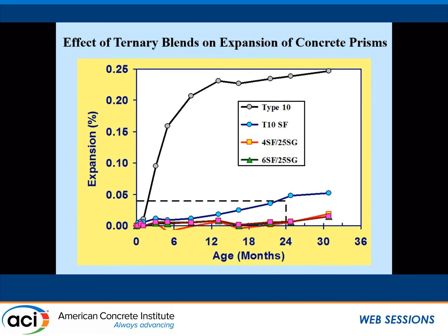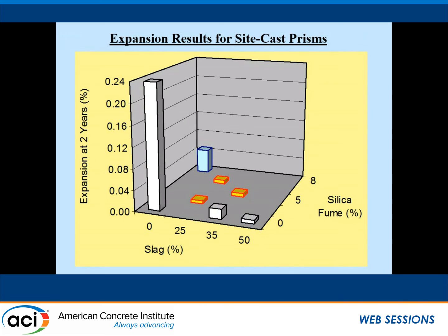The last time I looked, only the control mix was showing any kind of surface cracking or deterioration. So all of the blended cements have worked up to about 15 years. Obviously, time will tell if they'll be effective very long term. And that just shows the expansion.